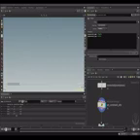So we can finish by creating the required attributes. Inside attribute wrangle, we have to run over primitives, which means we have to run over these polylines, and we have to create 2 string attributes. The first one is going to be called string at constraint name, and this is the name you have to match with the one you set inside the dop network.